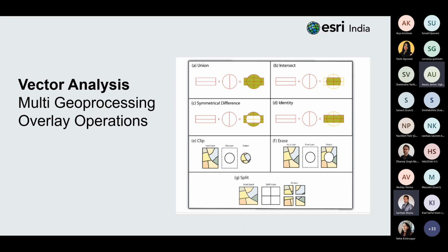The identity overlay method creates an output layer with the spatial extent of the input, but it includes attribute information from the overlay, which means that the input layers can be all points, lines, and polygons. However, the identity layer, which means the layer for which the entire attribute information is being provided, must always be a polygon dataset.